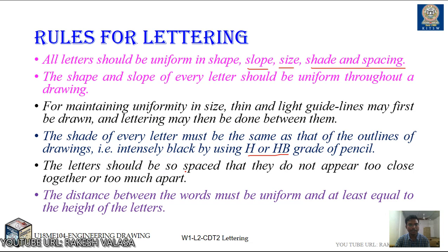The letters should be so spaced that they do not appear too close together or too much apart. The distance between the words must be uniform. Already we have given this in the mentioned table. So the students are required to follow a uniform distance between words, at least equal to the height of letters. These are a few important rules for lettering in engineering drawing.